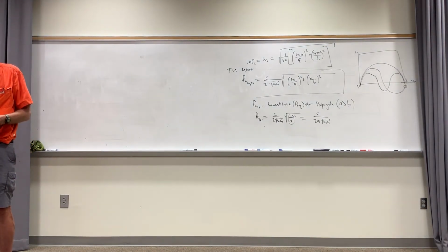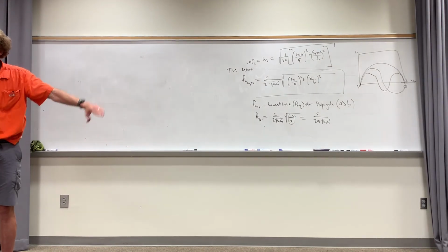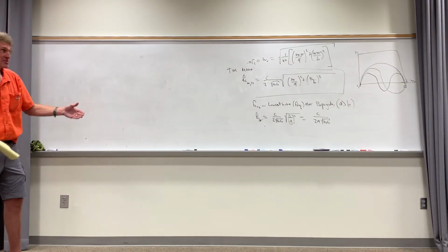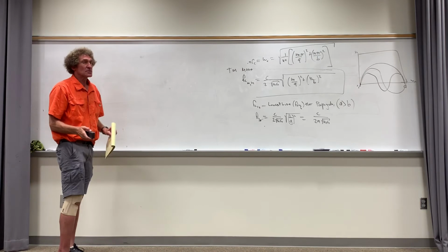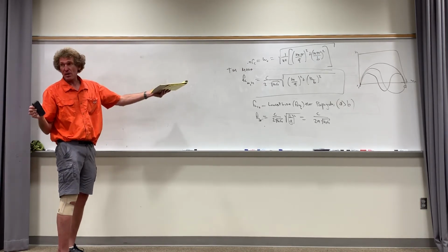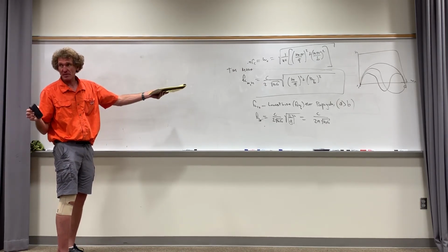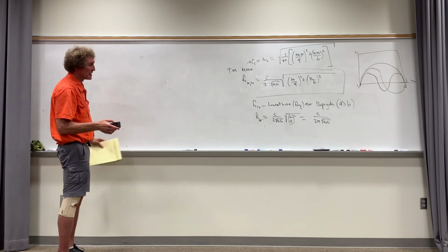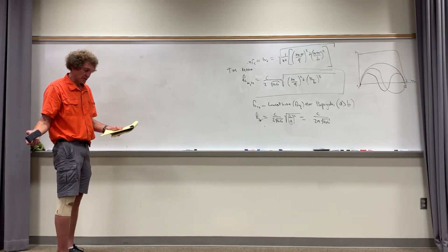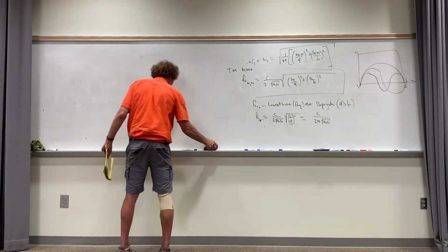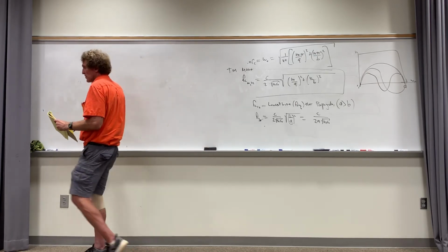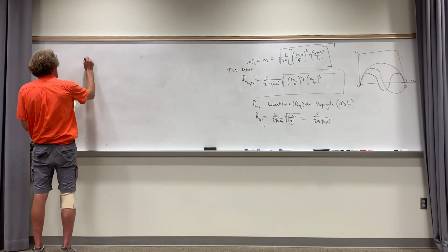Here we have an electric field component that is in the Z direction because the wave is bouncing or ricocheting as it goes down there. It's bouncing up and down the waveguide. So the equations are more complicated. Look at how the explanation for the E field in the Z direction is given. And then if you look at the E field in the Y direction, I'll just write this down. I'd have to go through the curl equation to get this,